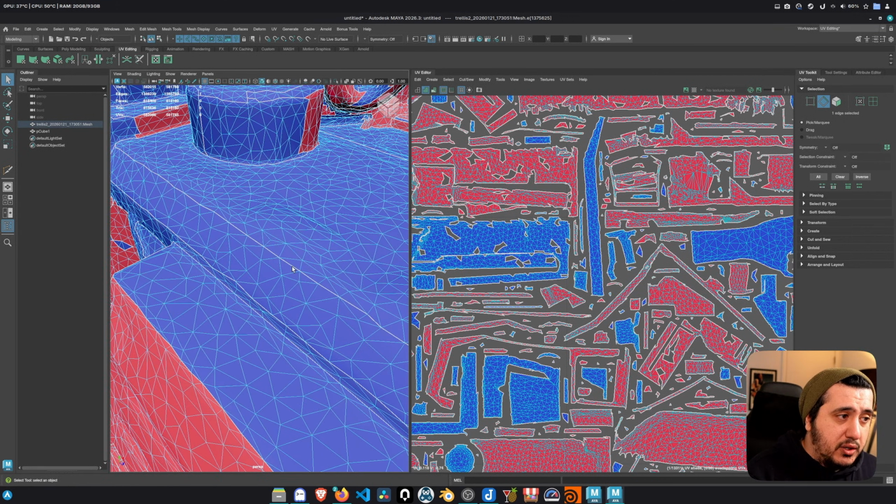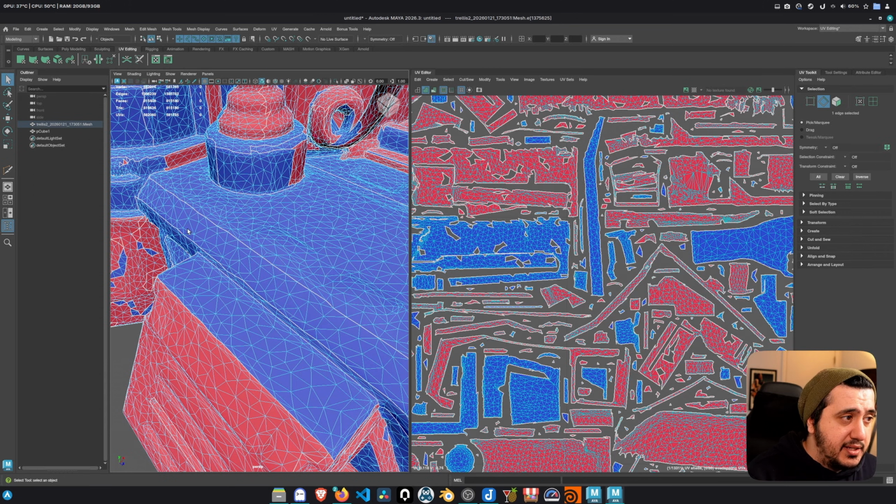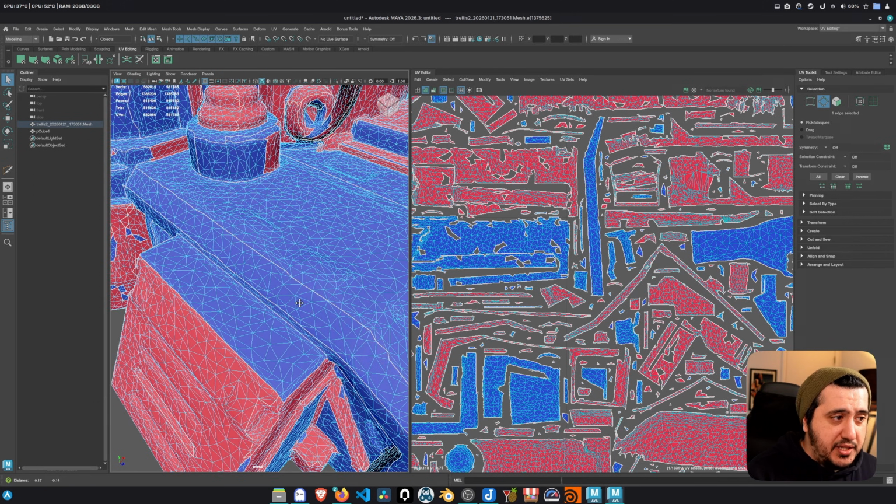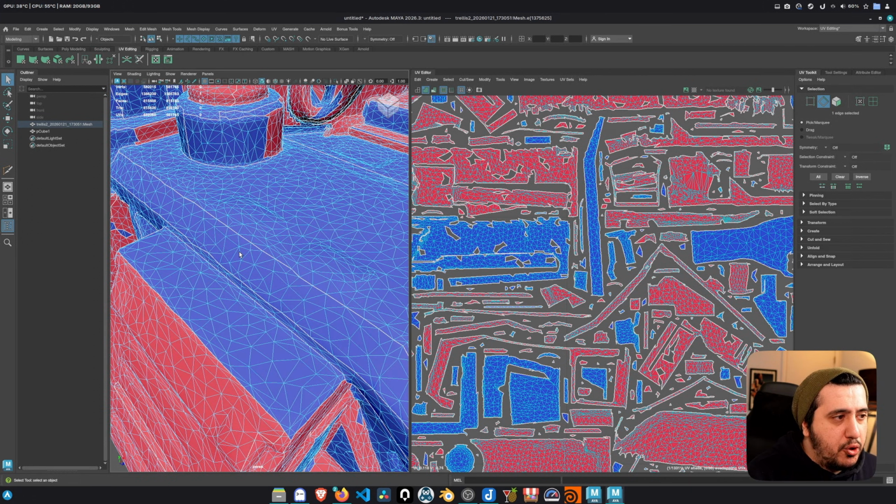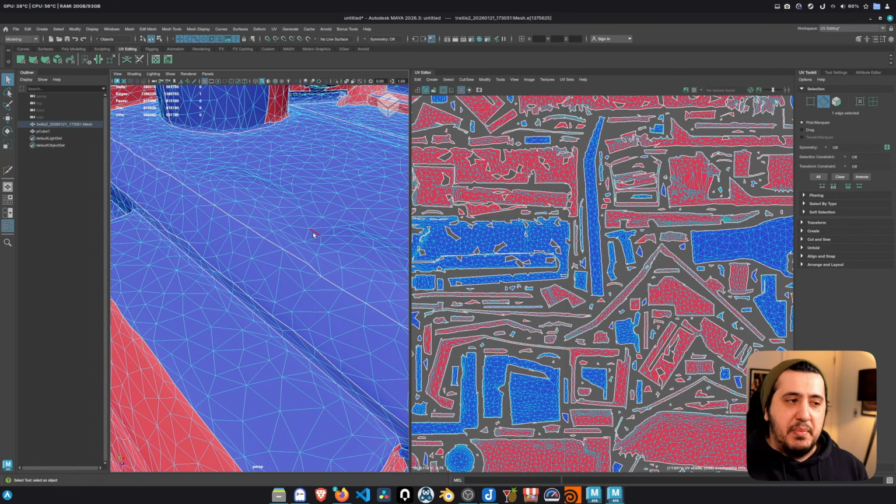If you are going to put a material in this UV shell, let's say this is going to be a painted metal, a red painted metal, and this shell is going to be metal, I am going to have a texture bleed. This texture is going to bleed into other material because of how it is being structured. I will never see that super nice, clean, sharp angle. I will give an example about this.